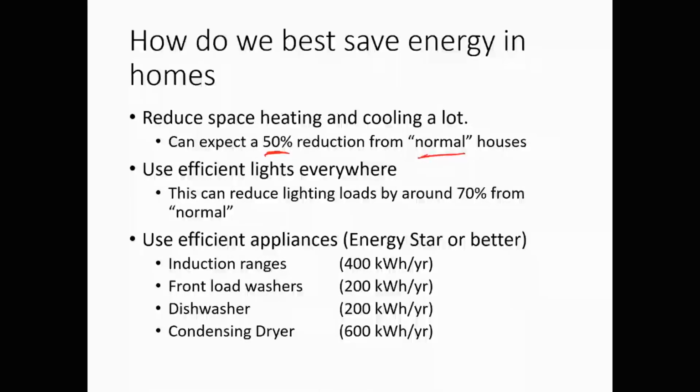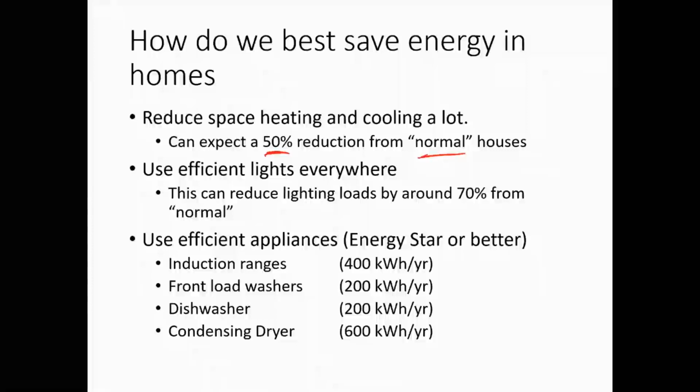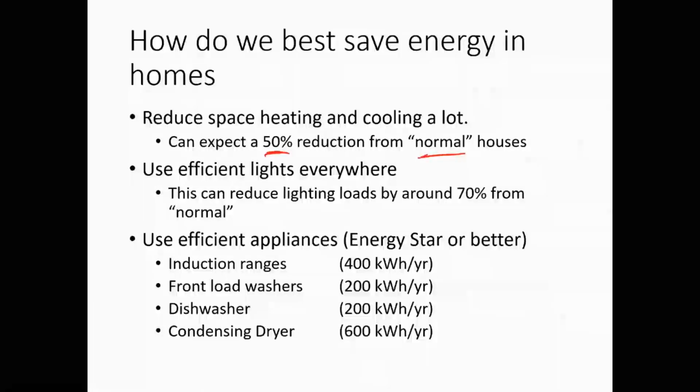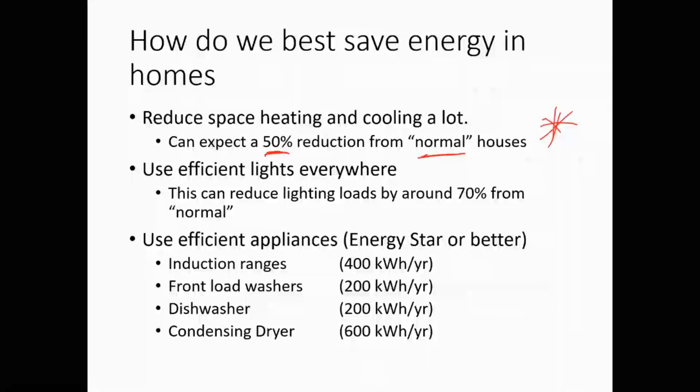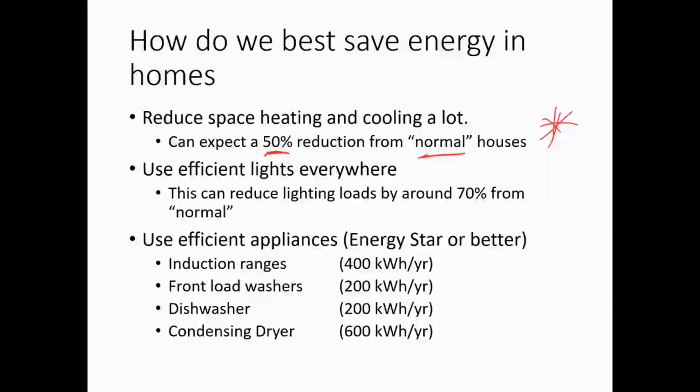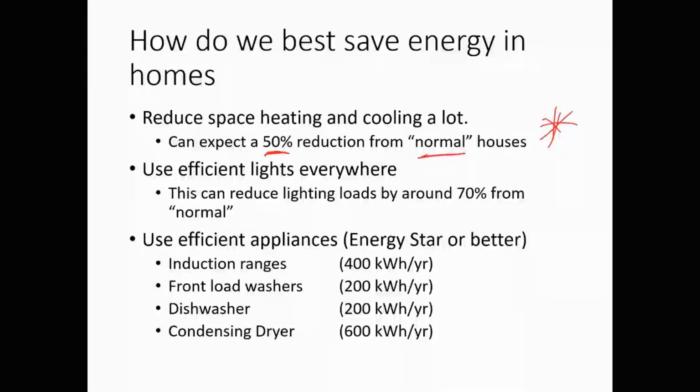The big thing to pay attention to here though is reducing our heating and cooling loads. And we can do this by passive means, by including higher levels of insulation. It is associated with a higher upfront cost, but over the life of the building, your increased insulation, stuff like that, it's not really costing you a ton of money. It'll pay itself back over time.